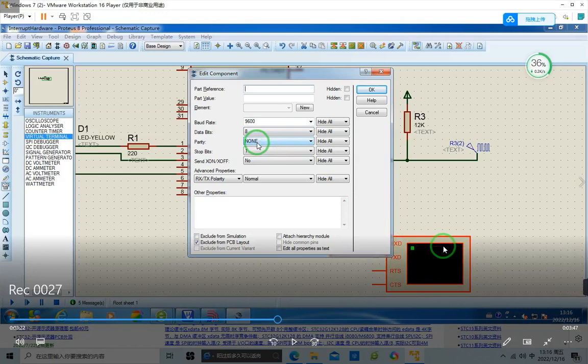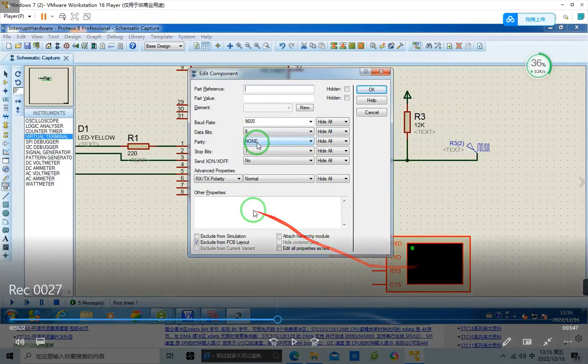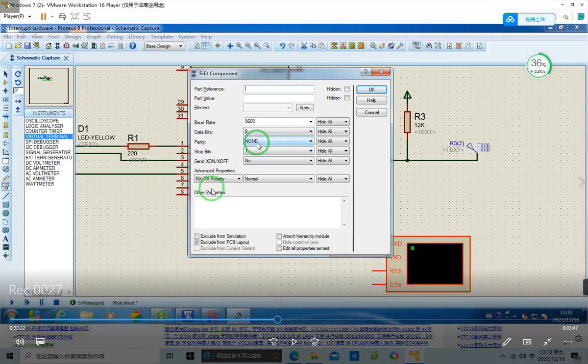So if it is used in a high reliability place, I suggest you to design CRC checksum. But you need to implement CRC checksum by yourself. You can copy those code from network and paste it to your own function and then debug. It's not very difficult.